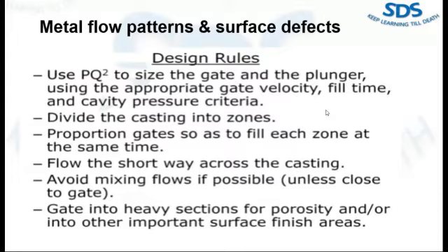Just put your casting shot on an A3 size paper, draw your gate angle, remove the casting or shot, and draw vector lines throughout the casting.